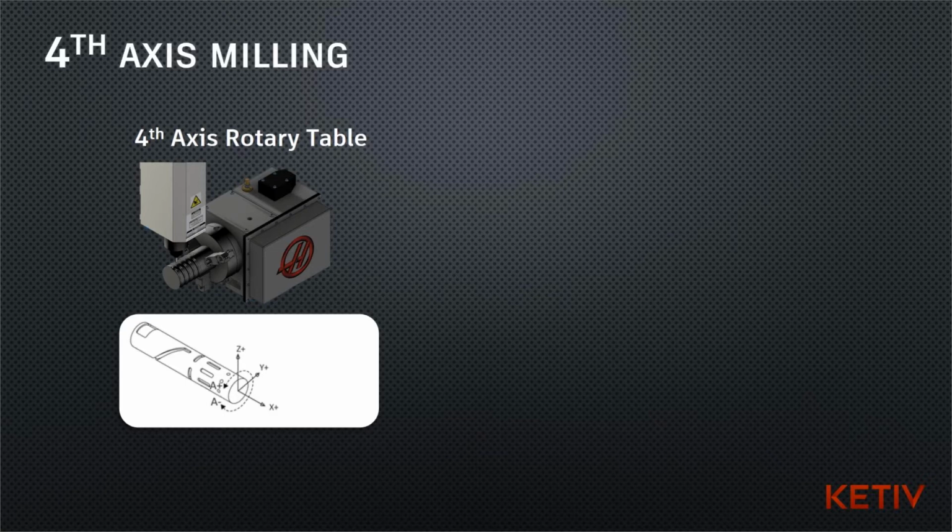So 4th-axis milling can be broken up into indexing or simultaneous 4th-axis. Essentially, indexing means you rotate the part, it stops rotating, and then you start machining. Whereas in simultaneous, you have all 4 axes working simultaneously.